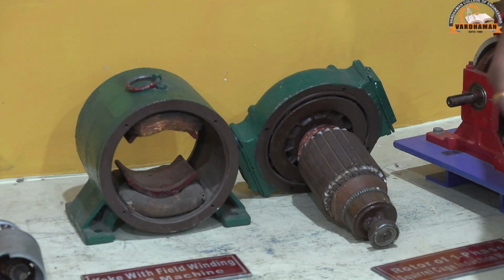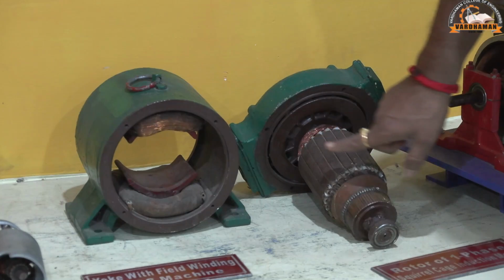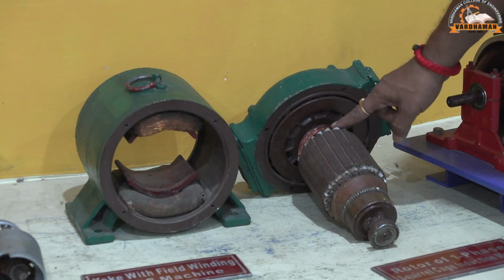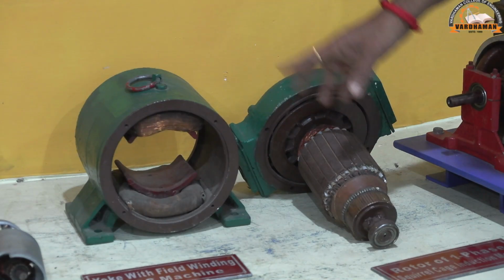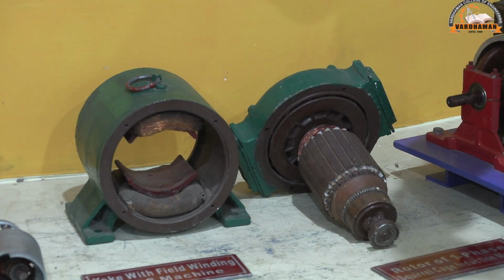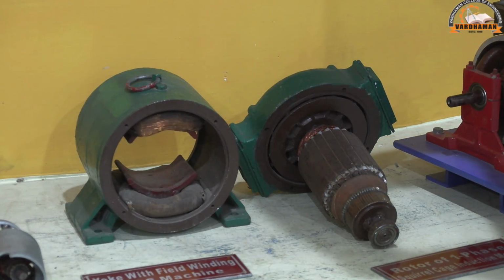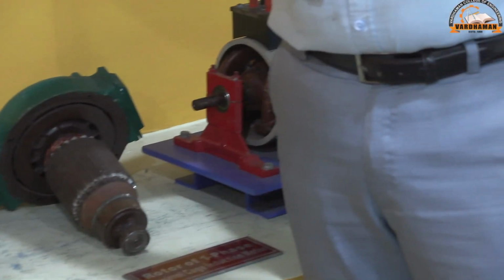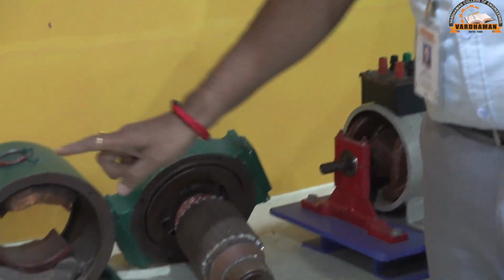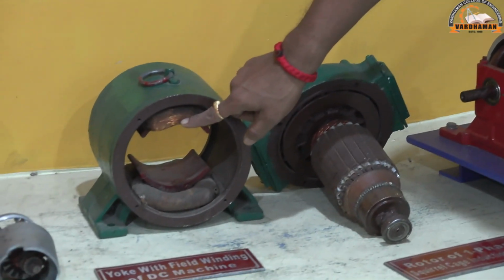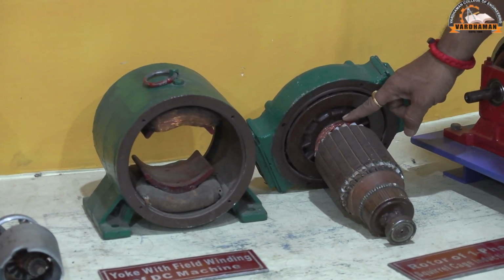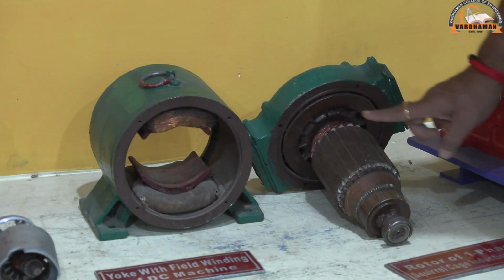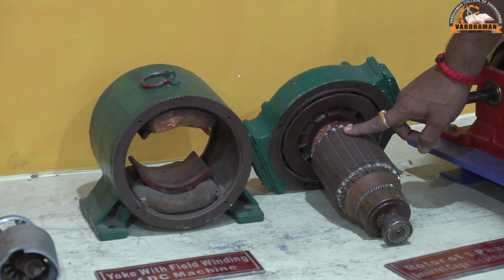In the case of self-excited DC motors, there will be a connection between the magnetic field coil and the armature. As I explained, there are two terminals of the magnetic field coil, and two more terminals for the armature. If you connect the two armature terminals in parallel with the terminals of the electromagnetic field coil, you have a connection between them. Suppose the starting terminal of the field coil is taken as F1, the starting terminal of the armature as A1, the ending terminal of the field coil as F2, and the ending terminal of the armature as A2.